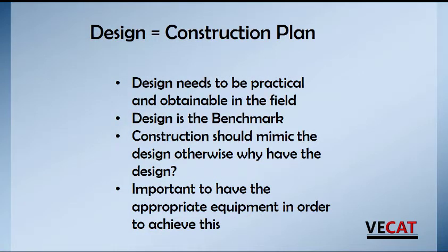First thing we need to do in order to be a successful reclamation is come up with a plan. If we don't know what's under the materials or under the asphalt, we don't even know where to start, how deep to go, or what we're going to run into. So we need to have a plan or a mix design.